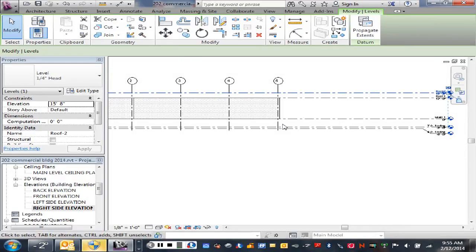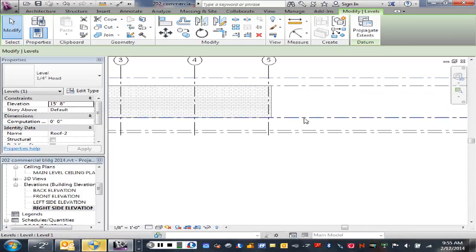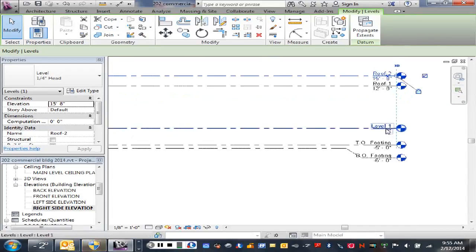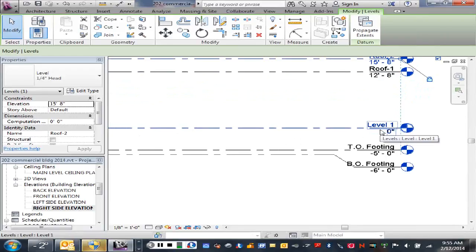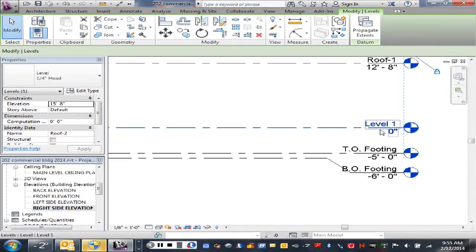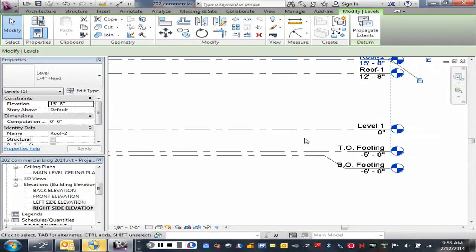So you're going to have to pour a topping on top of that to level them out. So level 1 will be the height of our precast. We'll pour topping on top of that, which is going to be 2 inches thick. Now that might affect our ceiling a little bit. Maybe our 10-foot tall ceiling now became 9 foot 10, because of that. That's not a big problem. We can solve that later.